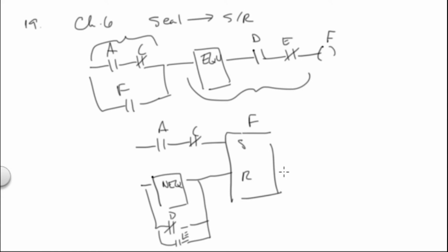So number 20 is a problem with going back and forth a set number of times, or until a weight equals a certain amount. So you go one side, hit a photo eye, time it, and then go back to the other side. And you keep doing that until you meet a certain weight in the box. So let's just call each of these passes a cycle.